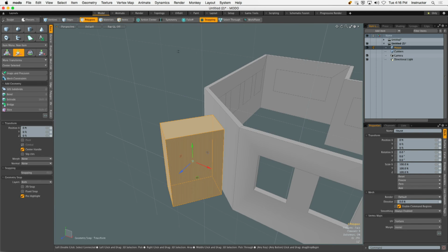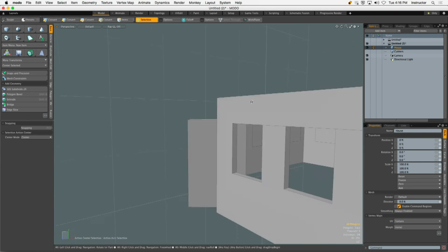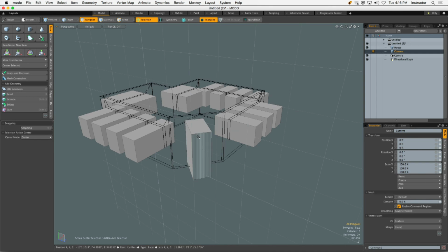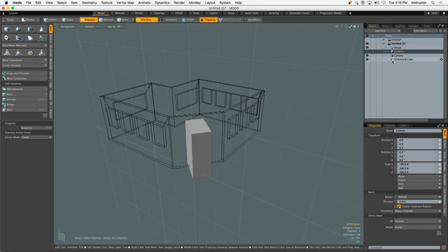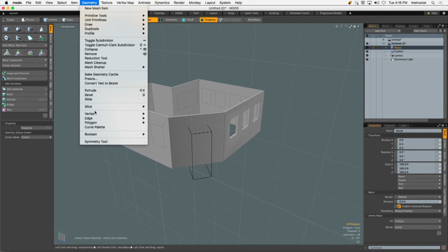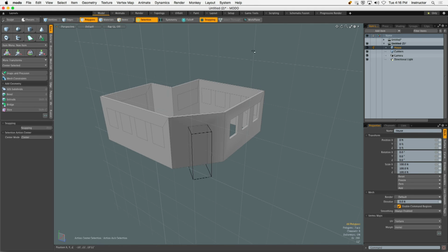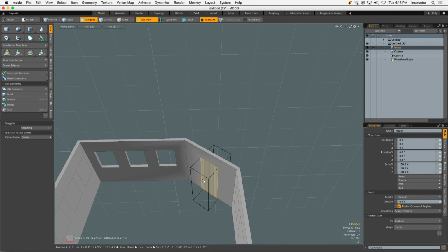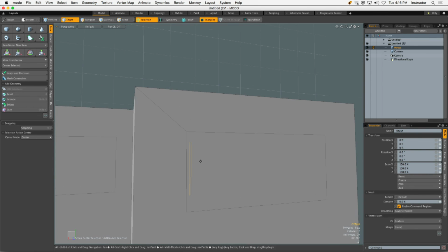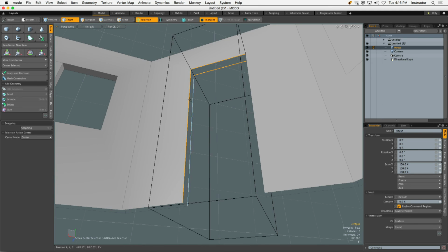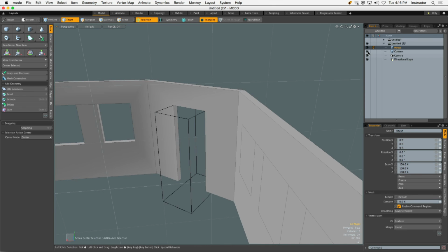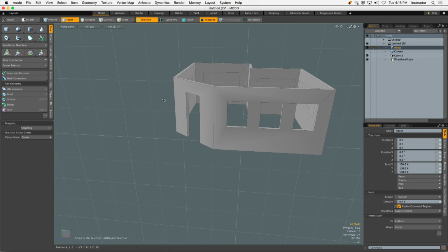I historically do this when I'm working with doors. I just push them a little bit further down. Awesome. And I'll run the Boolean once again, just on the doors this time. Boolean, solid drill, slice. Run bridge now, and everything's going to be quite perpendicular to each other, which is what we're after. Ah, groovy. Done. Happy camper.